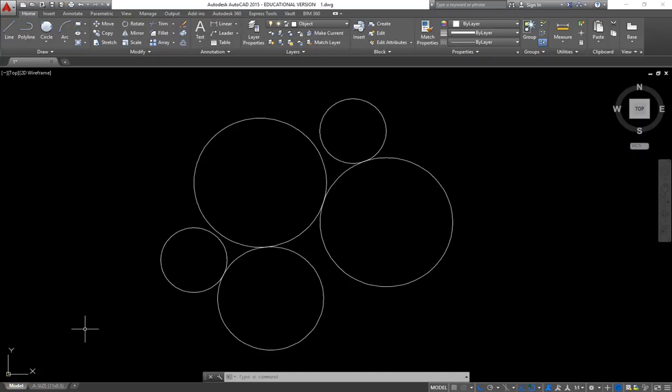Now for our next series of commands, we will need to utilize the Object Snap toolbar. This will allow us to snap to portions of the circles inside a line command. So we will choose a line command and then specify which snap we would like to engage before choosing another line segment. This is different from the Object Snap cursor settings, which are on by default and remain on no matter which command we use.